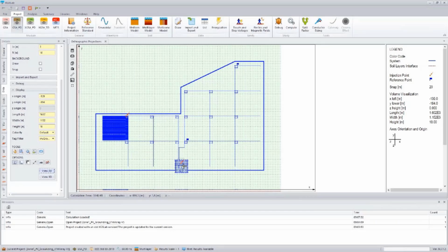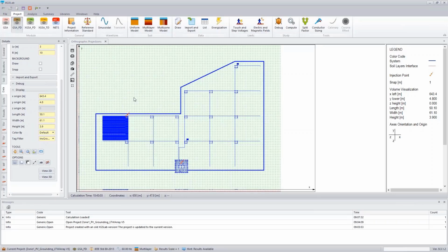And someone asked if it's possible to model this system without direct connection of conductors. And absolutely, I think the software that you need in order to do these type of studies has to be able to evaluate components that are not directly connected when you are really considering the transfer voltage to a perimeter fence. That's essential to be able to do that.